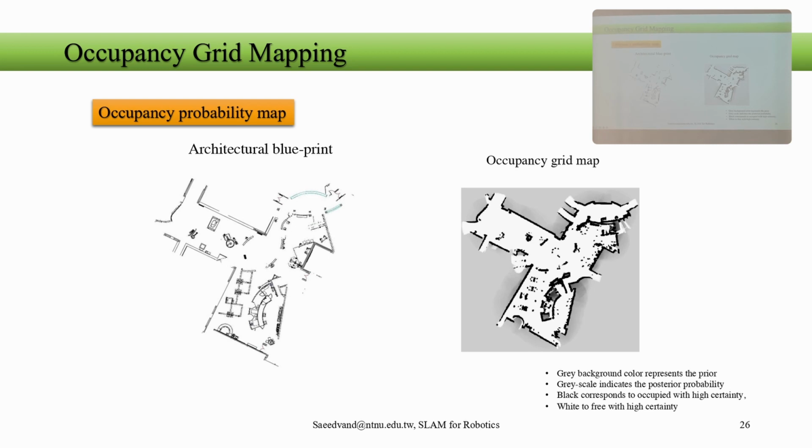By applying the same implementation and calculation from the reference book that we have, we can see the robot moving, and these darker points are more likely to be obstacles and walls. The ones the robot never saw are whiter. But we have some gray, more gray colors. Maybe it's not very visible here, but it's not just three colors. There are more grayish or lighter colors representing the probability.